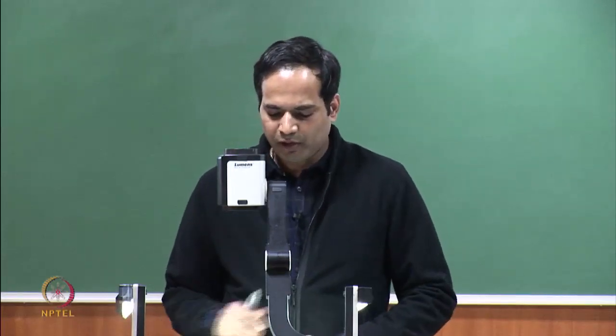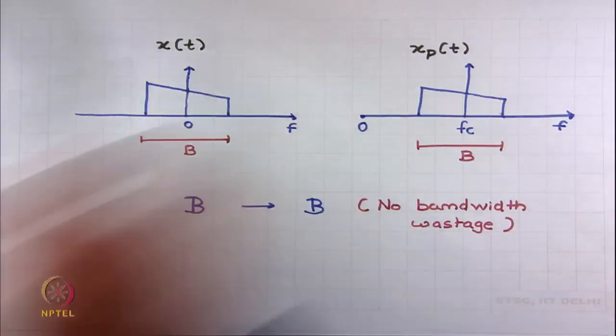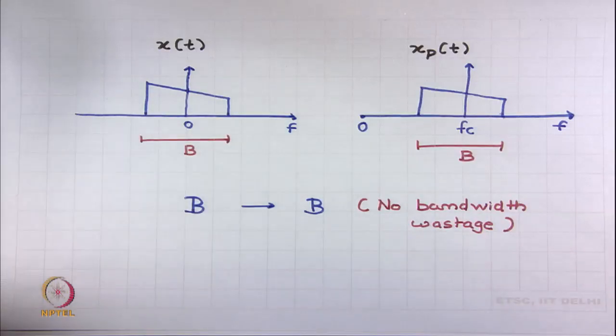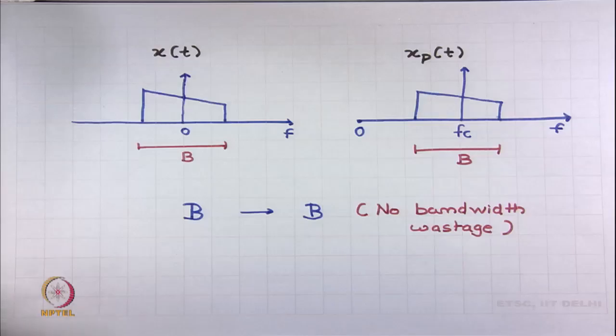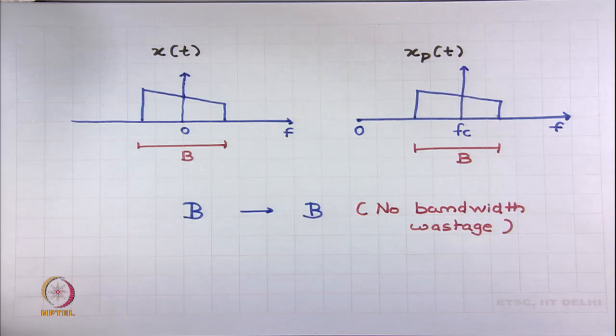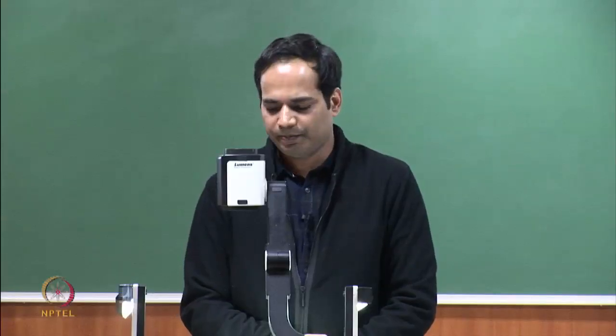The one picture that is important in this context is, if I have a complex baseband signal, it is complex, that is why the spectrum is not symmetric, and because this spectrum is not symmetric, it has no redundant information present, right. Its upper sideband is completely different from the lower sideband, and thus the information is present in both sidebands. And for bandwidth, we have also seen this, the bandwidth of this signal should be considered as the total support of the spectrum, including both the positive and negative sides of the spectrum.